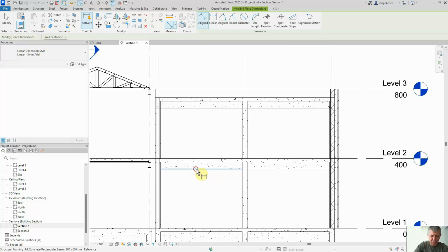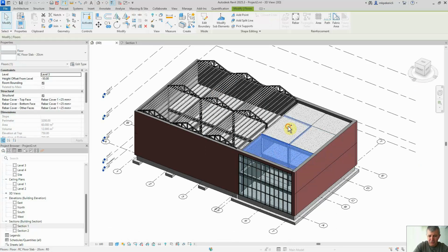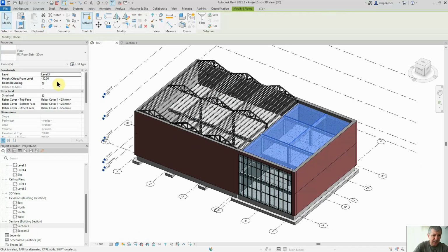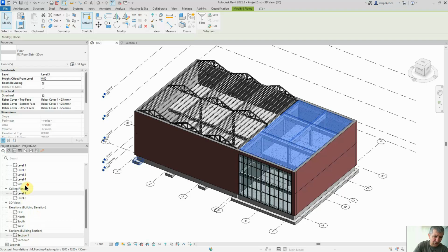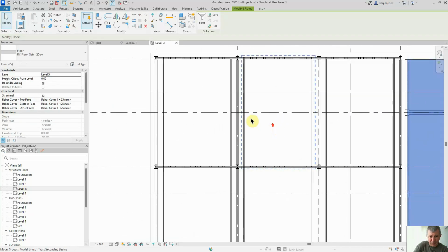How about the floor below? This is 340. You know what? I'm going to raise these. So let's first fix the floors. I'm changing my mind again. Let's make these 0, basically flush to level 3. Okay, then I need to select the beams underneath that floor, so I can use the structural level 3, is it? Yeah, and then